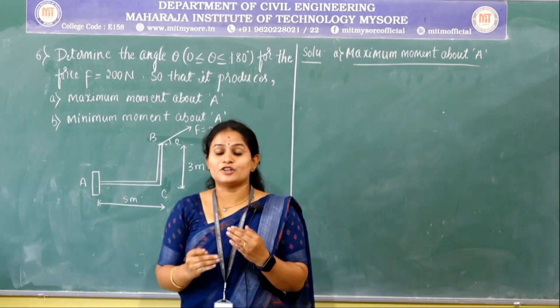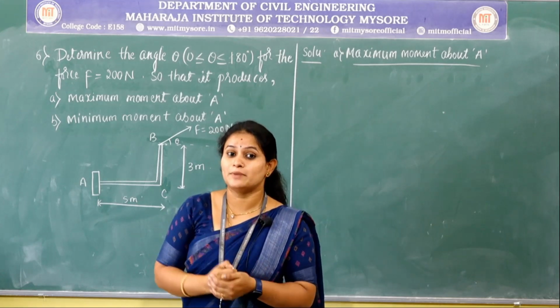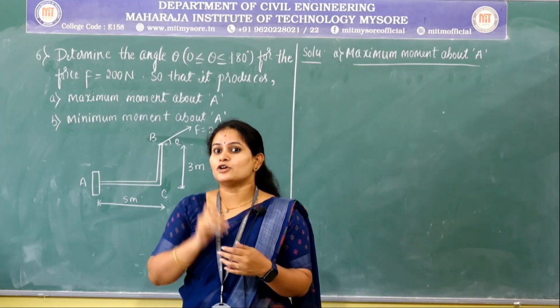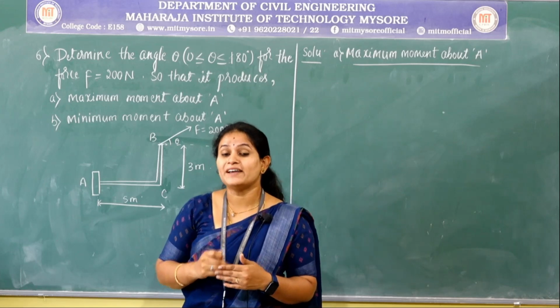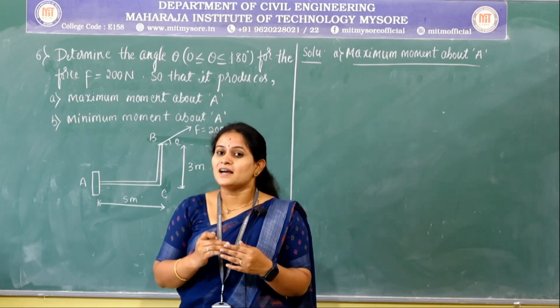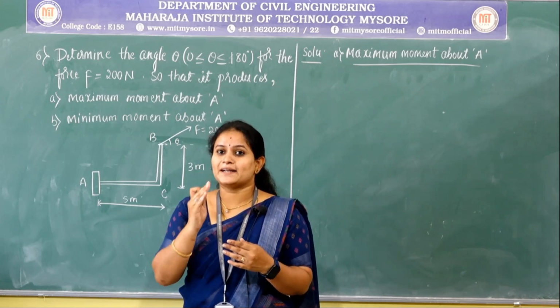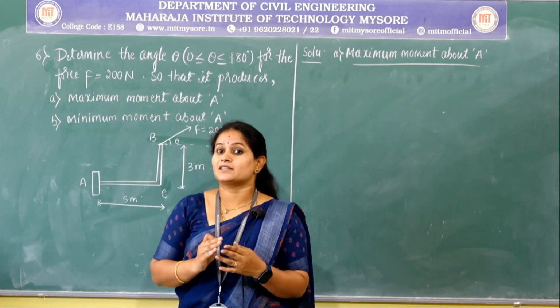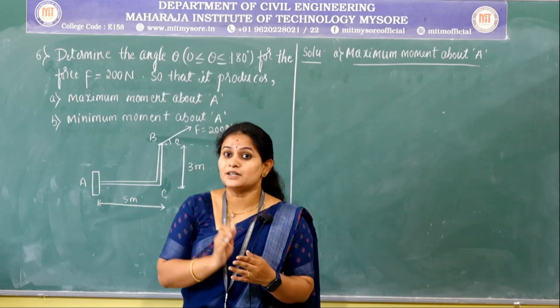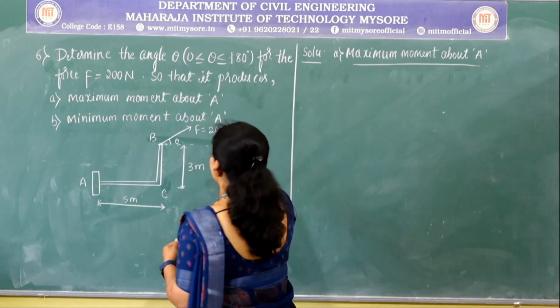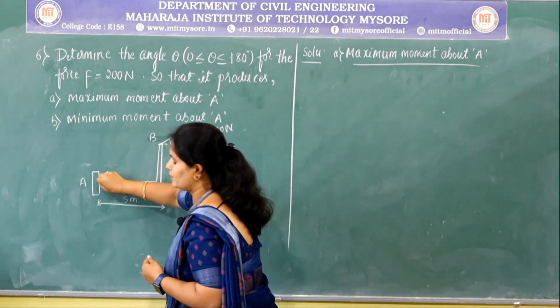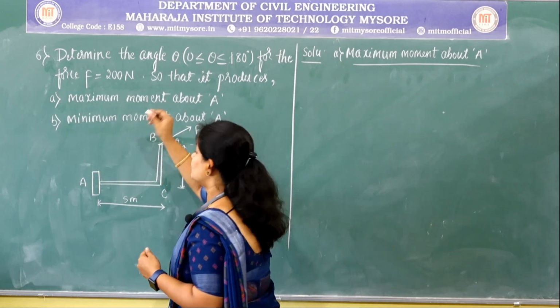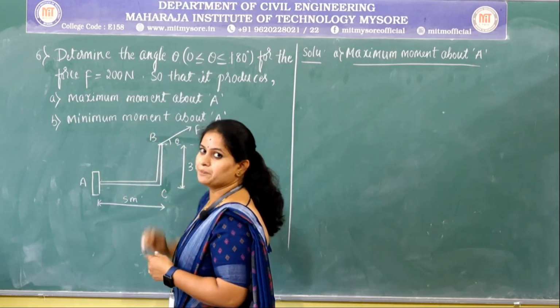When will a force produce a maximum moment? A force will produce a maximum moment when it is placed in a perpendicular direction towards the point. So, here we need to find out the maximum moment about the point A.